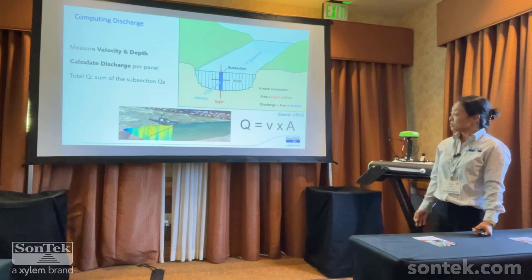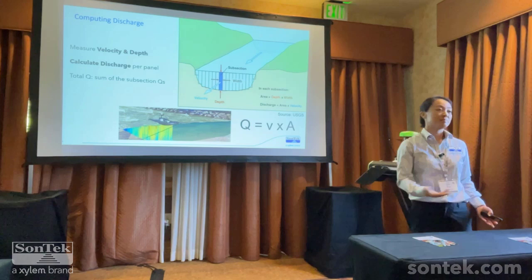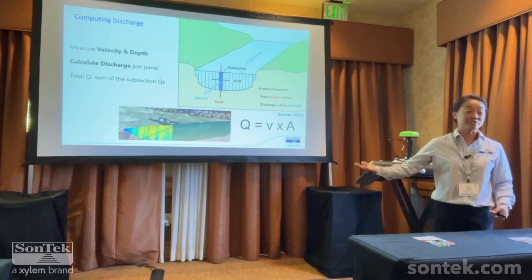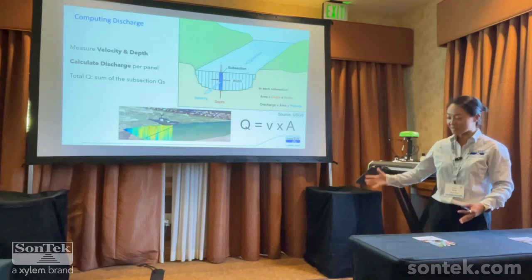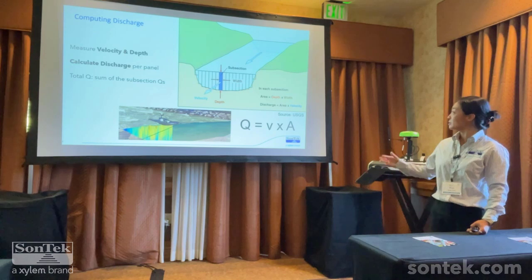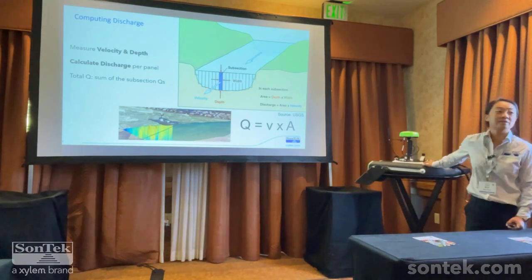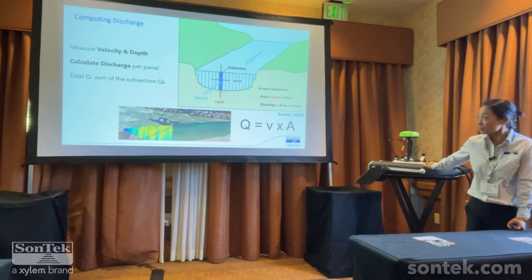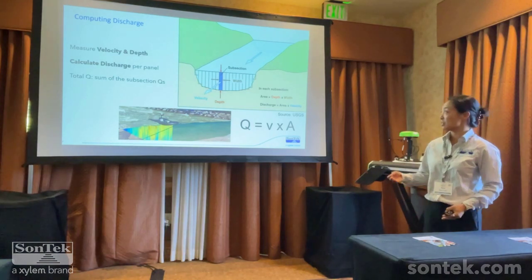All right, so in order to compute discharge, there are many tools and methods that people can use. We specialize in ADCPs. That's what we manufacture. So this is going to be purely the method using ADCPs here. So in order to compute discharge, our ADCPs will measure the velocity and the depth. So that's the actual measurement that we do. And then we use that information to calculate the discharge.